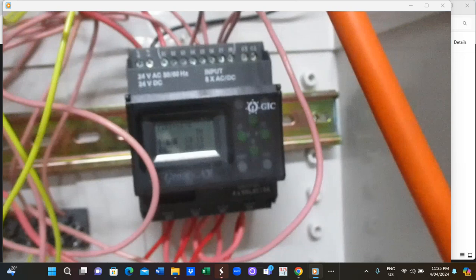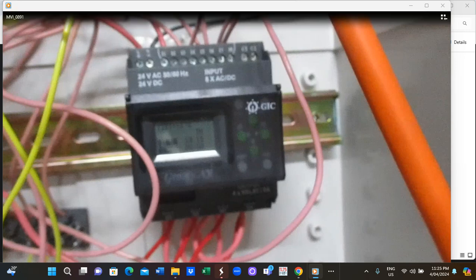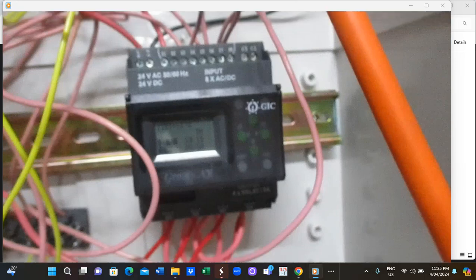And then you also need to connect the wires to the input and output devices. Inputs are the switches you press, and outputs are the coils. So inputs are there, you can see all the pressing switches, and output needs to connect to the lights and the contactor coils.